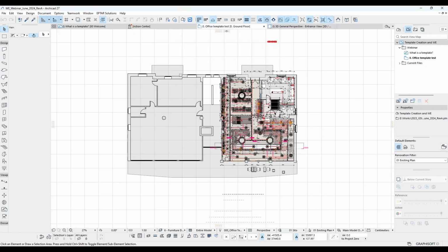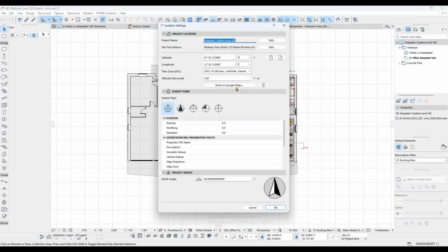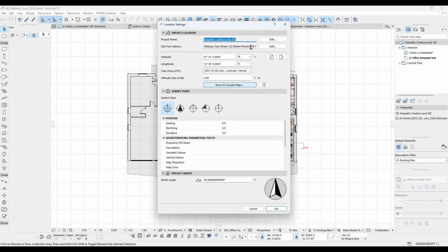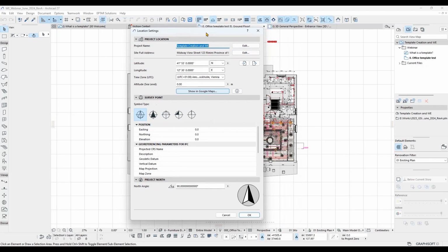And then we have the location and orientation. If there are some location settings that will already be repeating, such as a certain city, say you are working on projects in only some area of a city, and there you only have residential projects, or maybe only commercial projects, then you would have to relocate them every time if you do not have the template file.